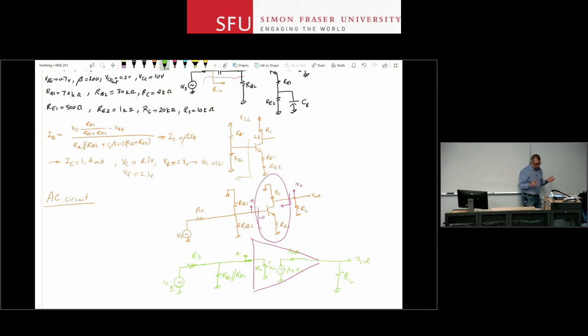I want to solve this circuit, okay? But because I've done the analysis for the common emitter stage already with emitter degeneration, and I have the formulas for whatever that is inside that triangle, I can see that right away. My life is very, very easy now. Because from the analysis I did above, I know that Rin is equal to R pi times 1 plus GM RE.